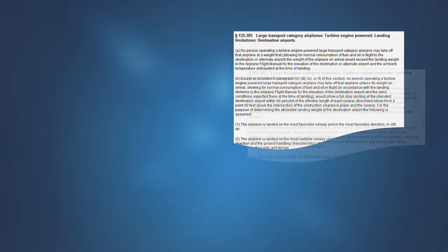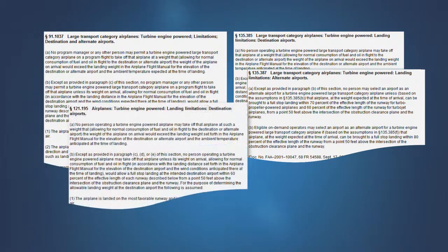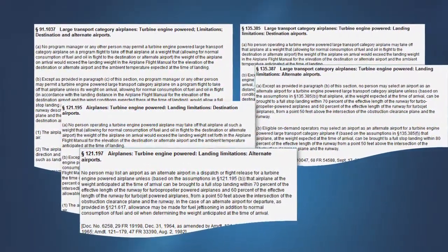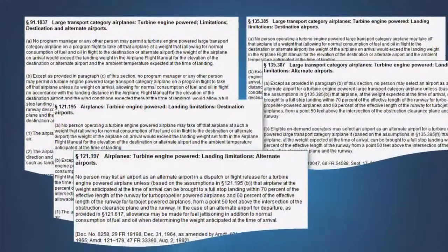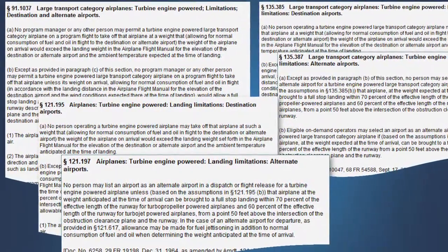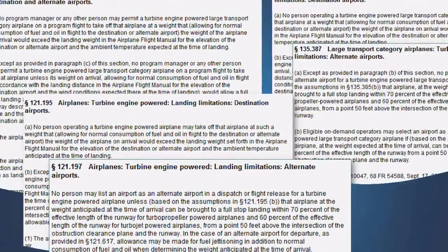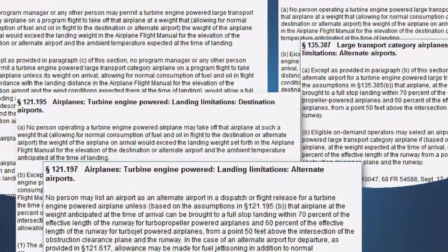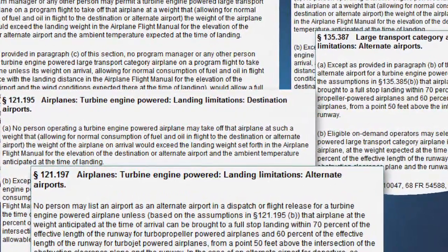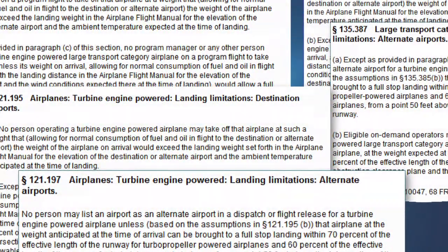The landing distances determined during certification are established with full awareness that operating rules require additional factors to be added when determining the minimum operational field lengths for landing during normal line operations. The operating rules for Part 121, Part 135, and Part 91K require that the landing distance demonstrated during certification remain within a specified percentage of the runway length available for landing at both the destination and alternate airport. As a result, these rules establish a minimum operational field length for landing. This requirement does not apply to Part 91 operators, but voluntary adherence to these rules is encouraged.